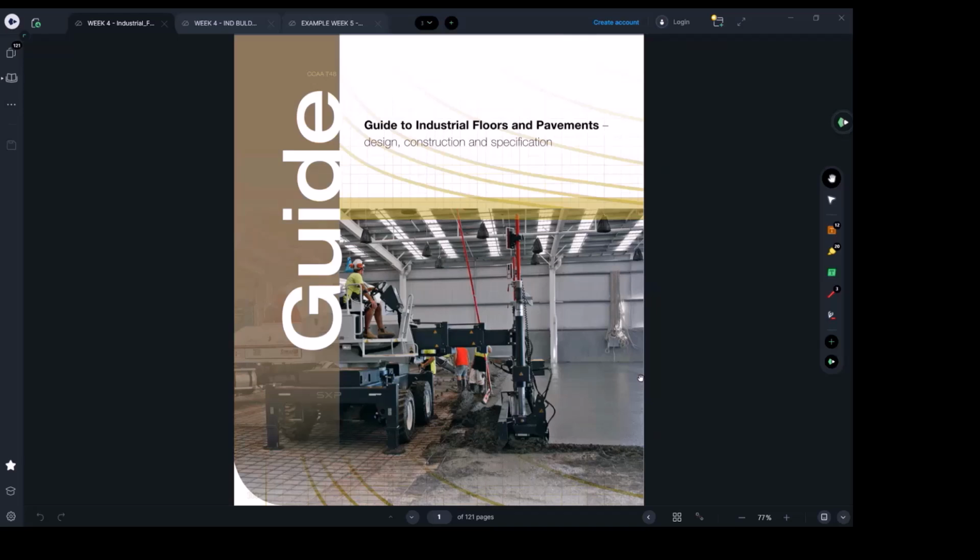Curing process: when you pour concrete, as it changes its status from wet concrete to hard concrete, it's going through a chemical process, and we need to make sure the water content will not evaporate quickly. So curing means we need to make sure the water stays in the mix by either spraying water or covering it. There are three main ways. One is spraying the mix.